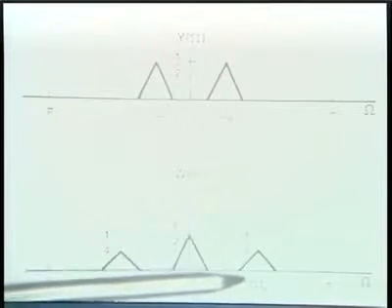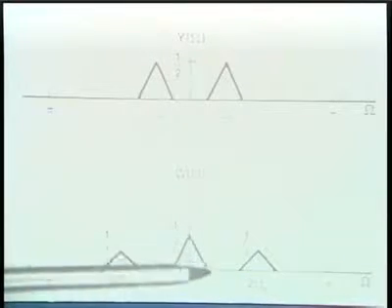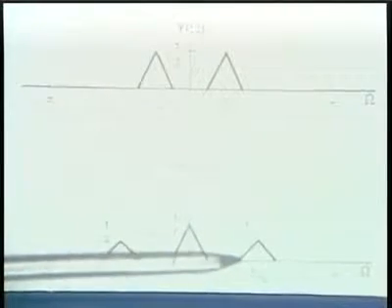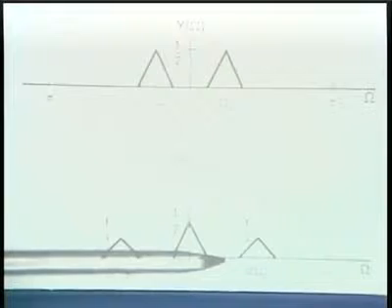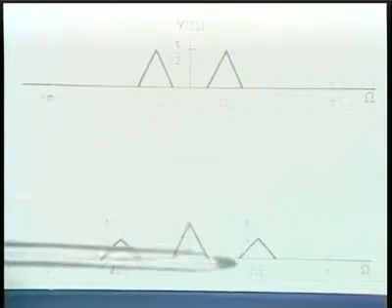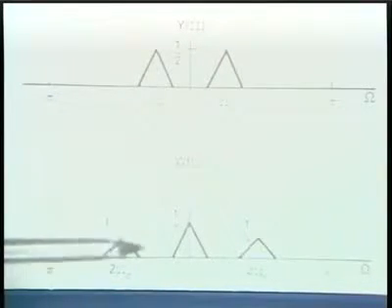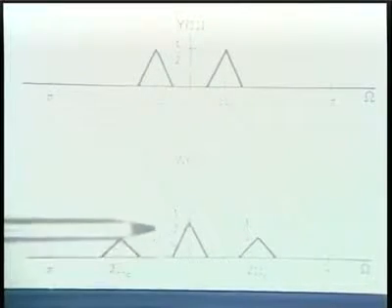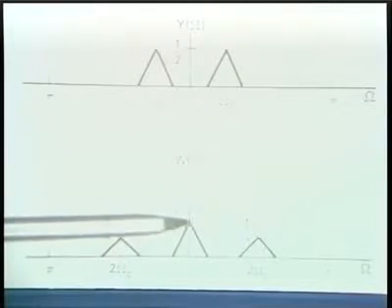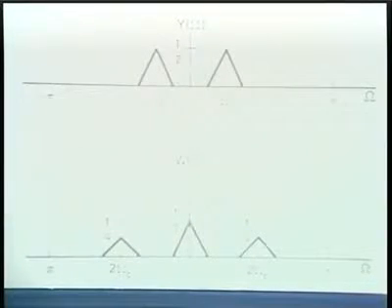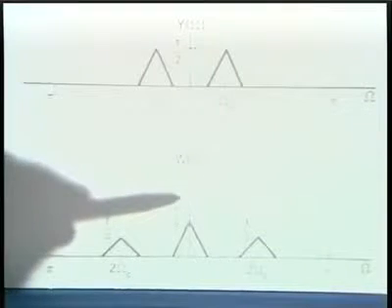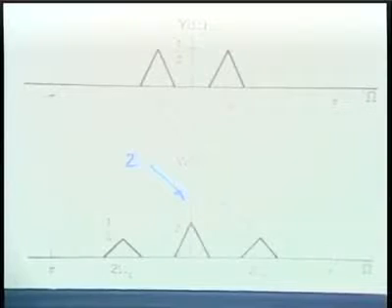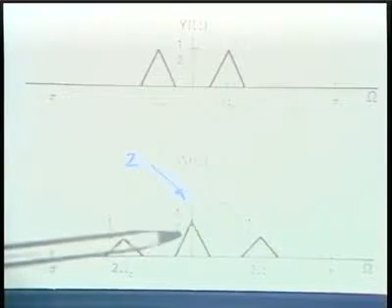And as long as the carrier frequency is large enough compared with the width of the original signal, then, as you can see, by extracting this part of the spectrum with a low-pass filter, we can, in principle, recover the spectrum associated with the original signal. And again, just as in continuous time, because this amplitude is 1/2, we would want to choose, for scaling purposes, a low-pass filter amplitude which is 2, to compensate for this factor of 1/2.